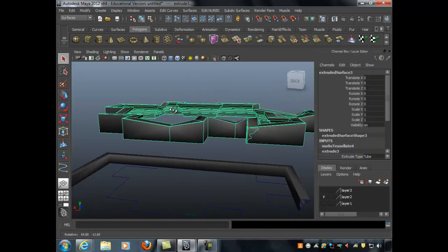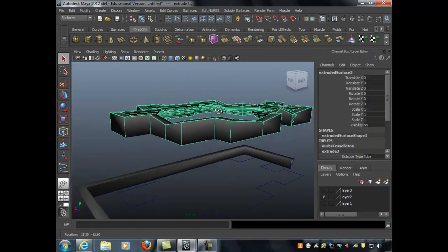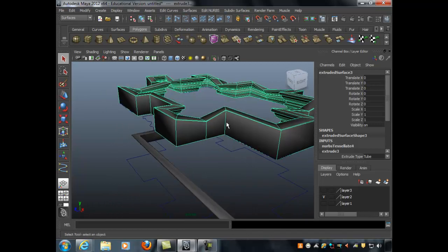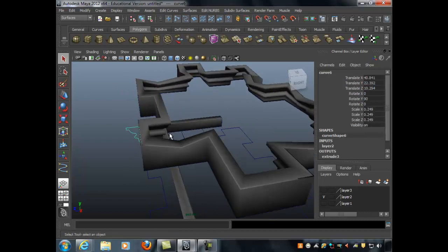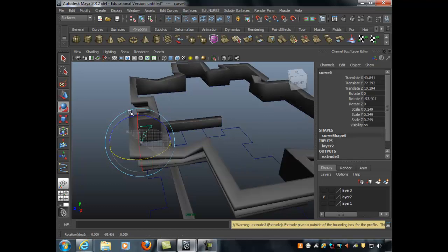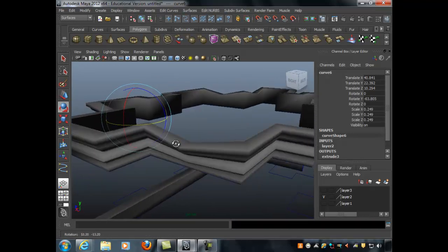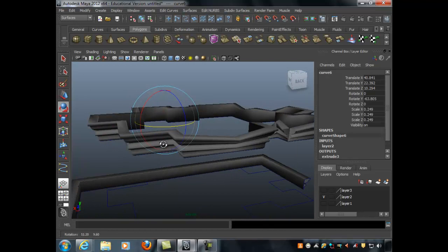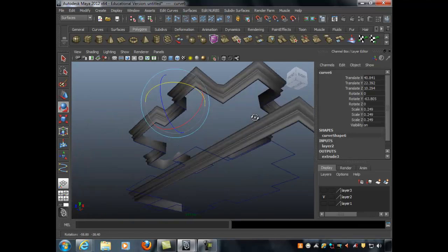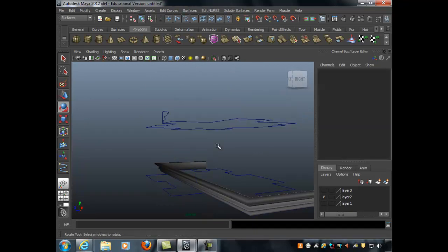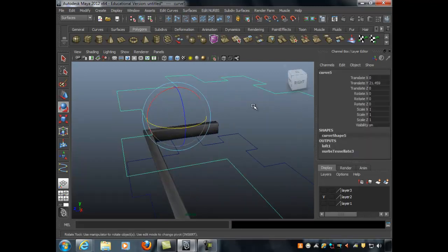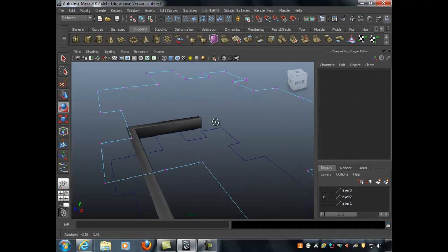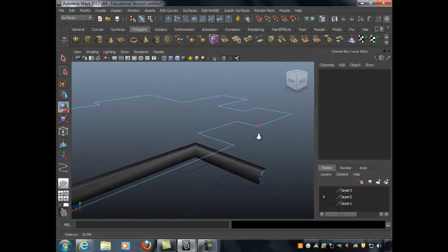See how this is all kind of messed up and weird? The reason for that is because I did not make sure that when I drew this shape, it was perpendicular to my path. And it did reverse it, so you say, well, oh no, all you've got to do is reverse it. But even when I reverse it, look what happened. It's all jangled and messed up, all right? And the problem with that is that, again, you have to draw these so that they're perpendicular to the start of your line, right? And the way you find that is right here.